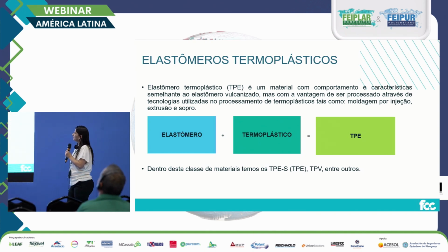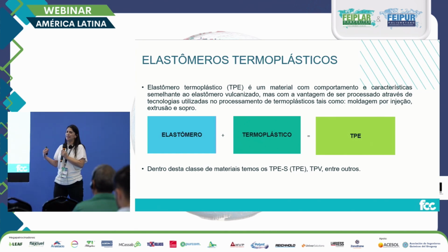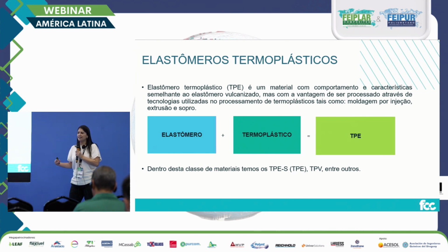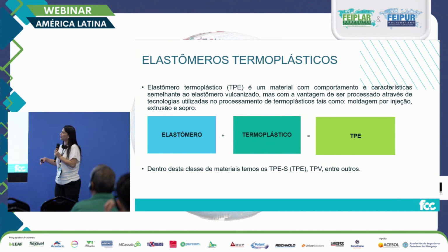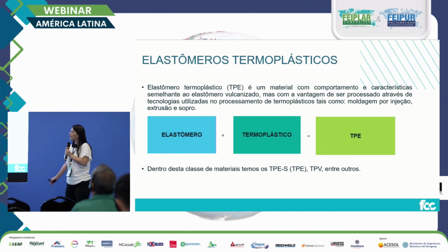TPE behaves and has similar characteristics to vulcanized elastomers, but there are advantages in being a material that is easy to process through blowing, extrusion, or injection.